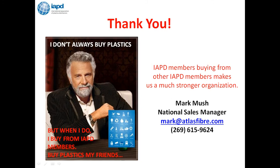I might butcher what this says. Do you have any experience with frac balls? How do G10 frac balls compare to Torlon 5030? Are there any advantages? I would say that the frac ball market is pretty well past G10 and G10 FR4. It was a hot market for 3 or 4 years, but they're going to many other kinds of materials now, including some materials that are being imported that will dissolve on their own at a certain point, so you don't have to go down and drill them out. G10 and FR4 was a great market for frac balls for a few years. Grades like Torlon and some other materials seem to have eroded that market quite a bit. We don't see a whole lot of demand for that now.